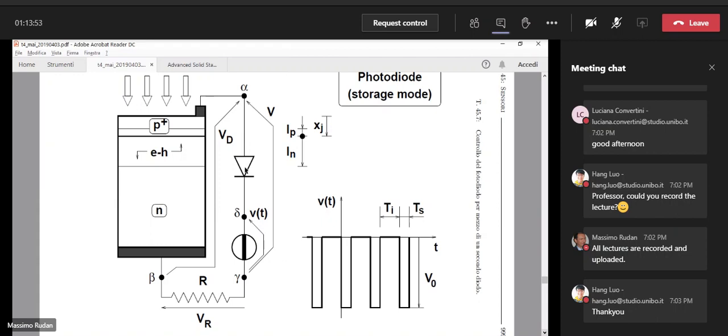Then at some point we bring the voltage generator from the very negative value of the voltage to 0. Okay, so all of a sudden point delta goes to voltage 0, whereas point alpha was negative. Okay, the switching diode has no time to rearrange the charge. So essentially the switch diode becomes a diode in which the N side is at 0 and the P side is with a negative voltage. So the switch diode is reverse biased, so it becomes an open circuit.